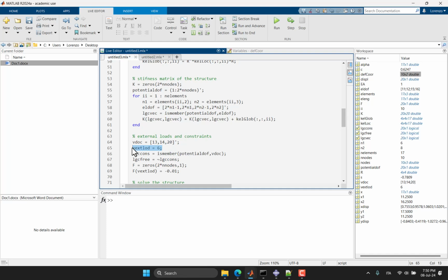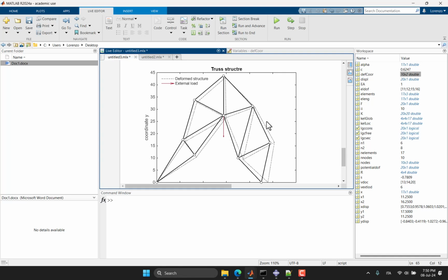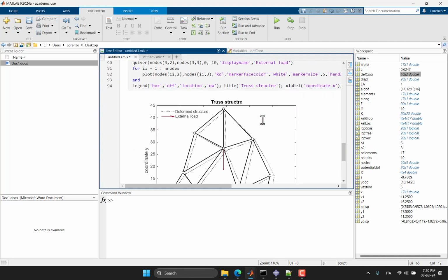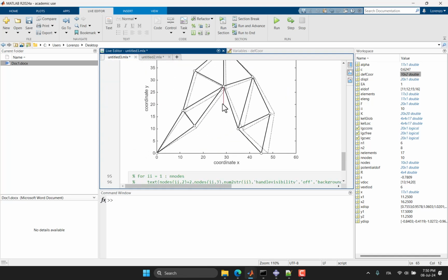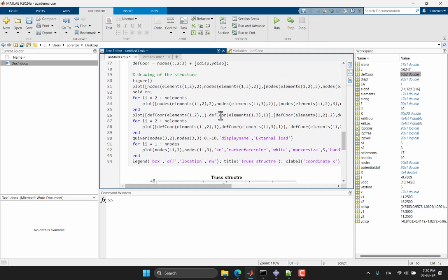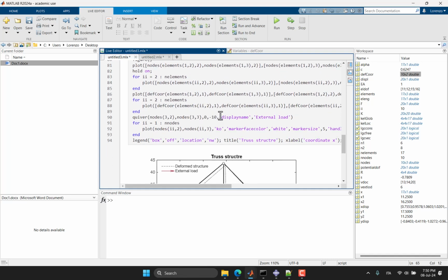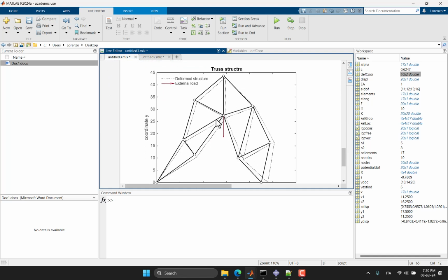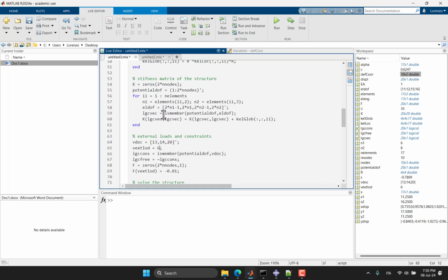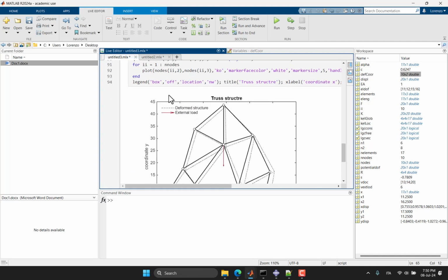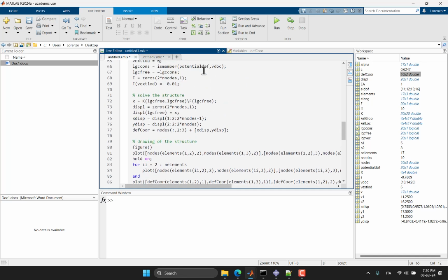The external load, of course, can be also a vector. I mean, you can have many loads applied in different positions. Recall that truss cannot withstand bending, so you must be sure that the structure can deform in a way that is producing a force in a way that it's absorbing energy, otherwise the stiffness matrix will be singular and the code doesn't work. But it doesn't work because of the physics of the problem, not because the code is broken.